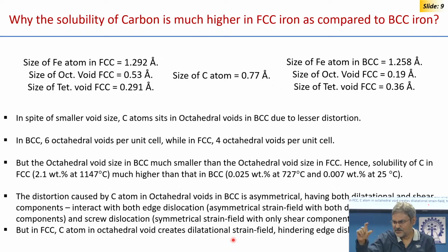This side also, it is basically equal. You will find in FCC the atoms are at equal distance. So, sorry, in FCC you have to put it at the edge center. If you put it at the edge center, you will find the face center atoms are at a by 2.